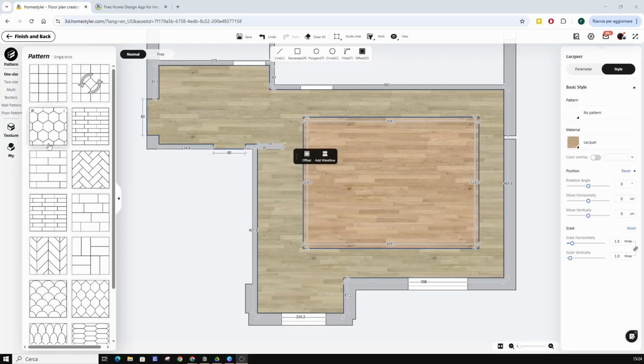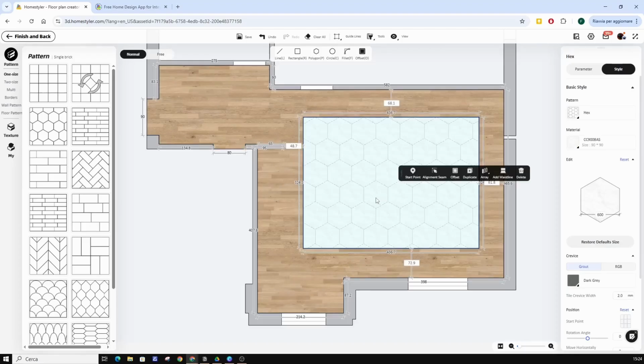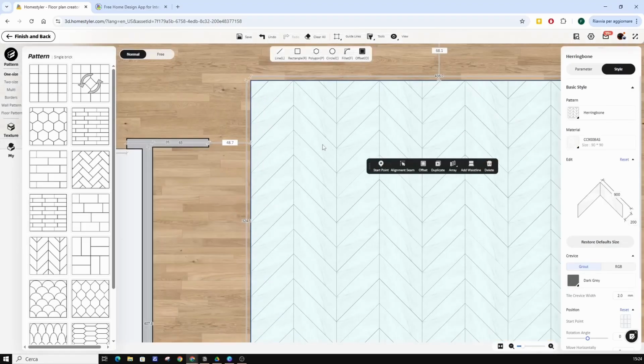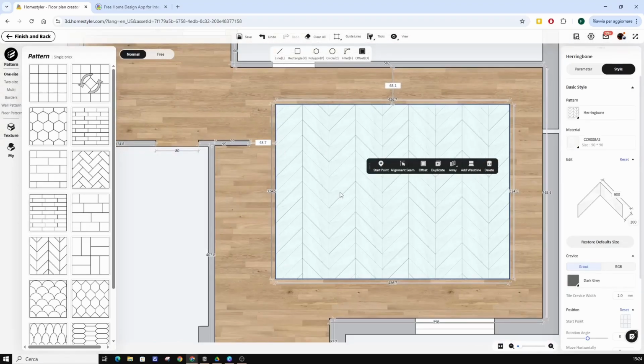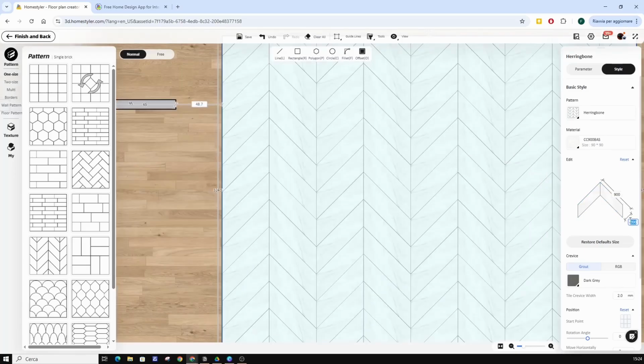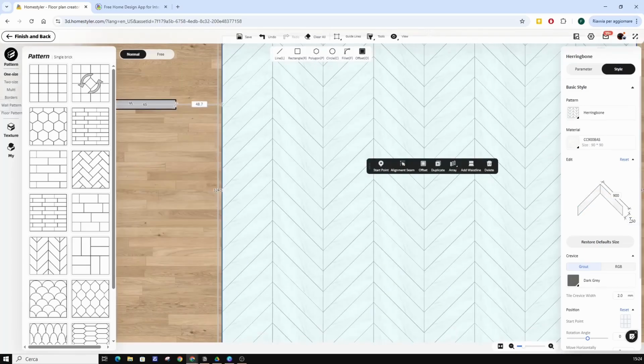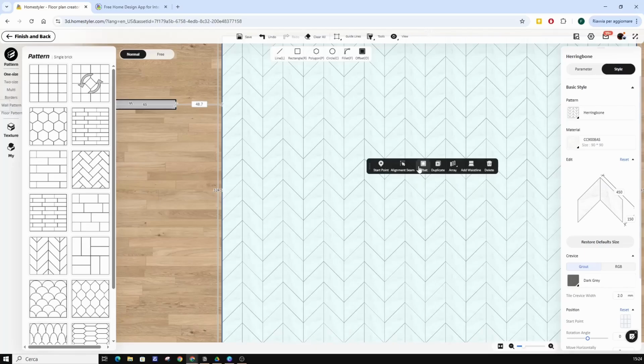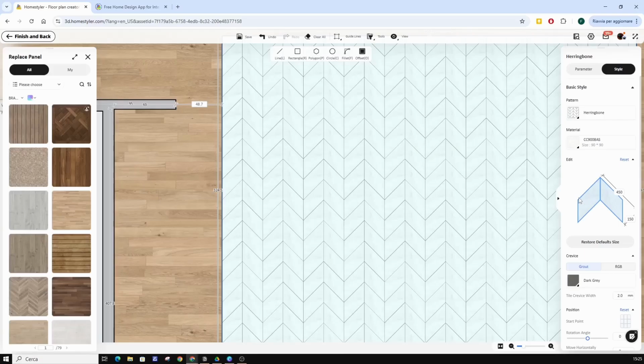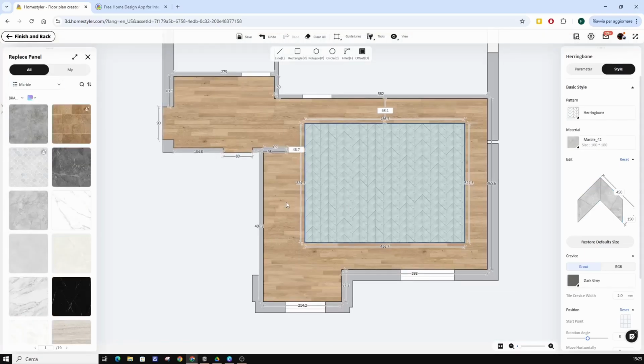We see that the first thing proposed is a window with various types of laying schemes. When we have chosen a laying scheme, we can act both on the dimensions, which are expressed in millimeters, and on the color of the tiles. We must select the tiles and choose a material. In this way, the material will be changed.